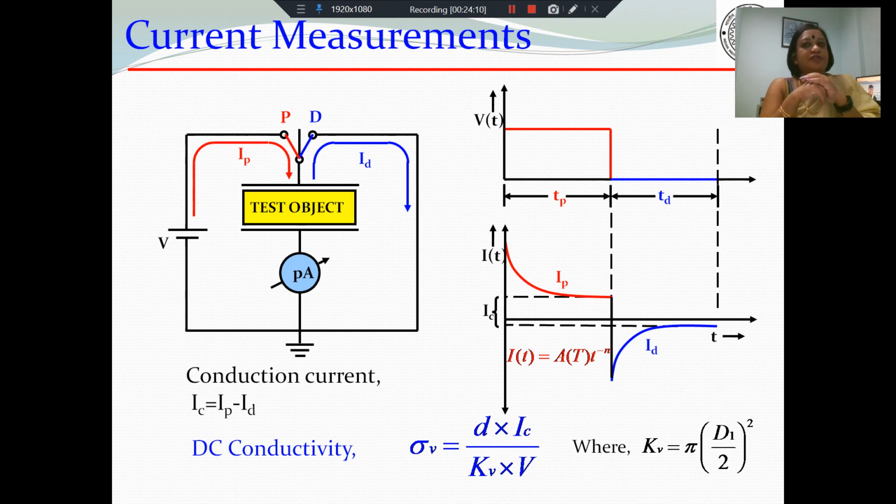If you do not have a frequency dielectric spectroscope, it is possible to use the time domain spectroscopy, that is, these polarization and depolarization current measurements, to obtain permittivity as a function of time and therefore permittivity as a function of frequency. That is also possible. So one method is a substitute for the other with its inherent advantages or disadvantages, but no matter what, both should give you the same diagnosis.